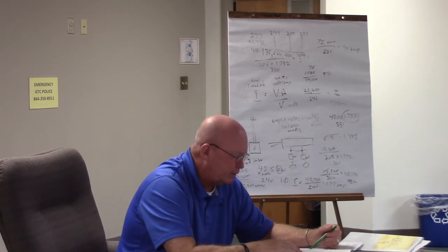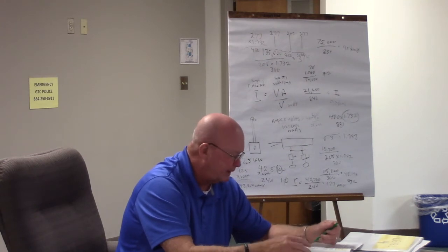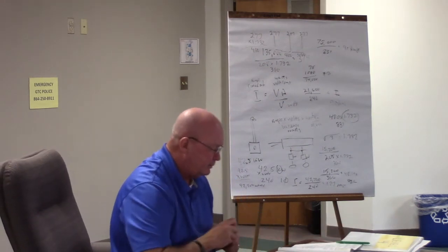What's the secondary current of a 1500 kVA 3-phase transformer with a voltage rating of 480? They want the secondary. It says multiply 1500 times 1,000.